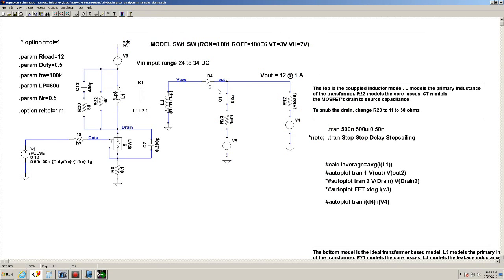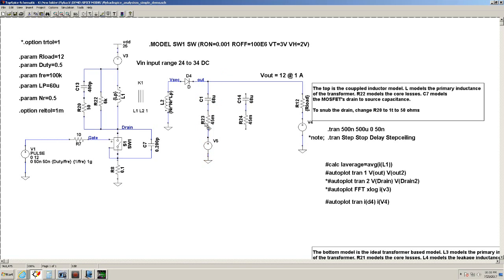And so this is why you see a bunch of capacitors hooked up in parallel. Basically, they're paralleling the capacitors so they can get a low enough ESR. So let's move that there.